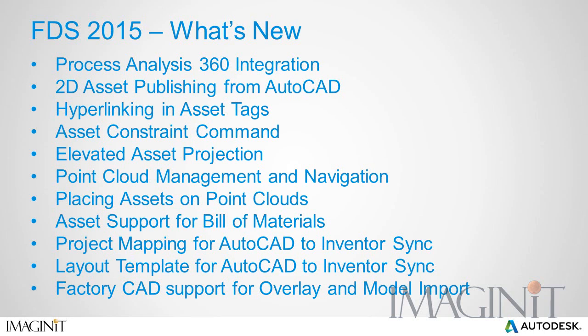Assets are now fully supported in the bill of materials, and we can get all of those key parameters that we use to change the sizes of our asset to show up now in the bill of materials. There's new project mapping options and layout template options. When you sync from AutoCAD back into Inventor, certain project files will be honored no matter what, as well as a layout template will be used no matter what the current state of Inventor is. And there's now new support for FactoryCAD. We can now utilize FactoryCAD as a DWG overlay, and we can now import models generated from FactoryCAD into Inventor.